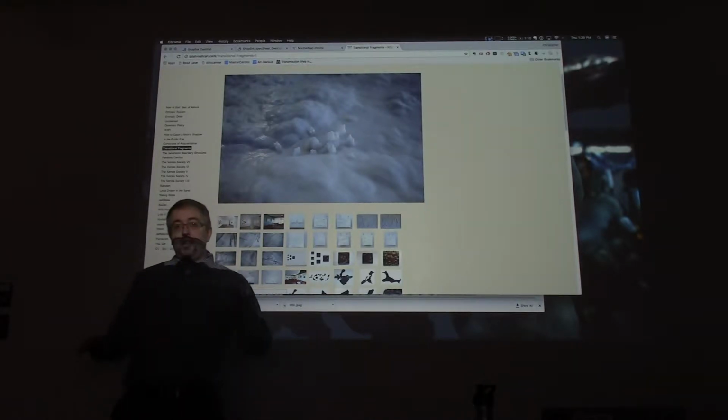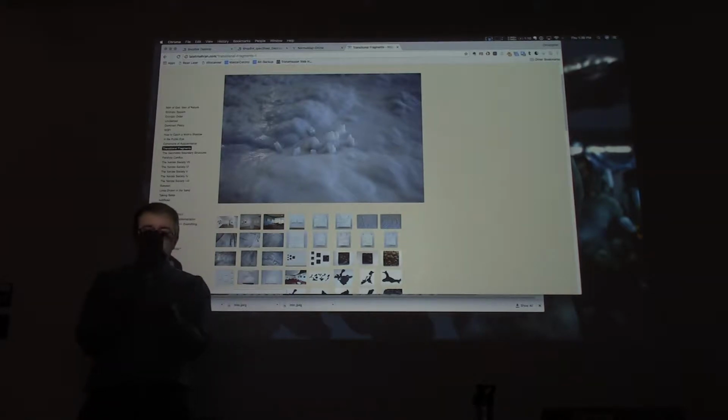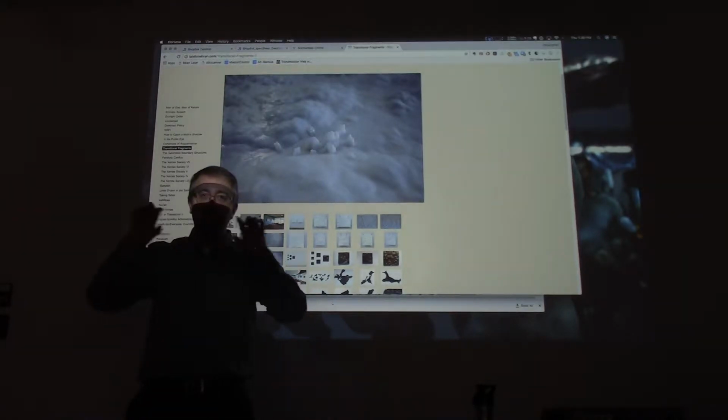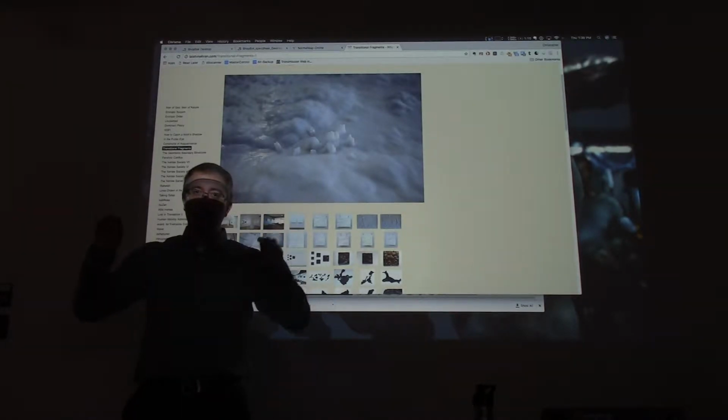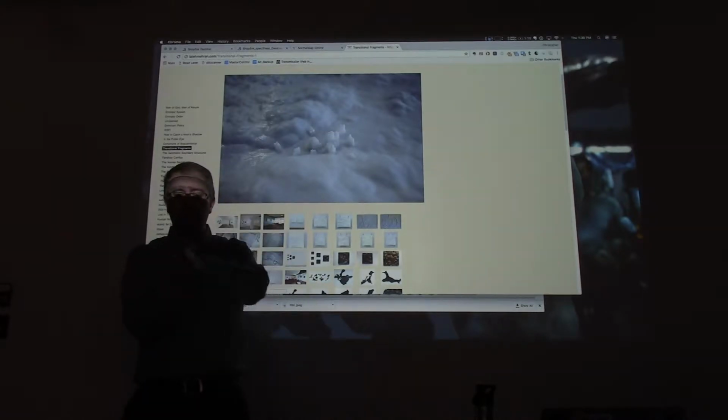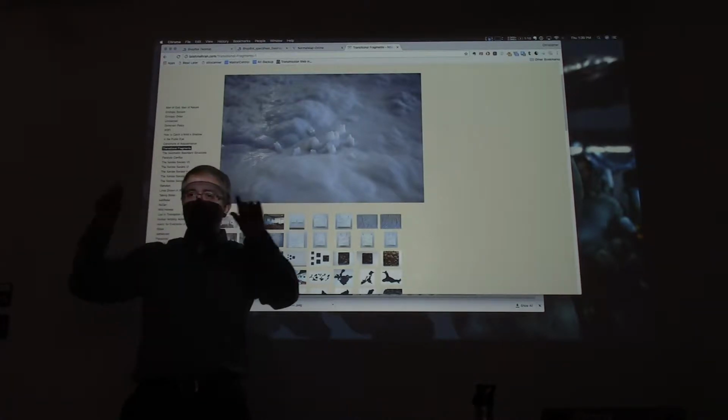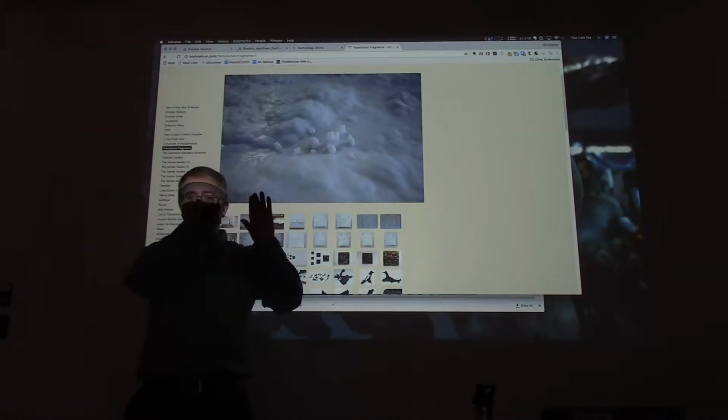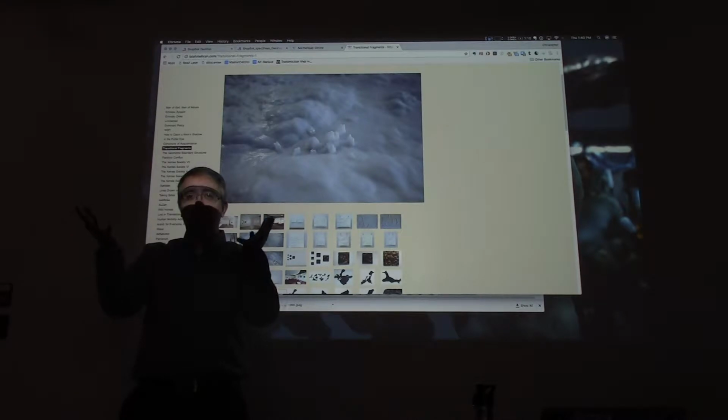During that process, because the material has built-in stresses from the way they make it by running it through rollers, which changes the molecular structure and makes a flat product, the second you start removing all of the top end of the product and do nothing to the back, the whole thing wants to curl up.